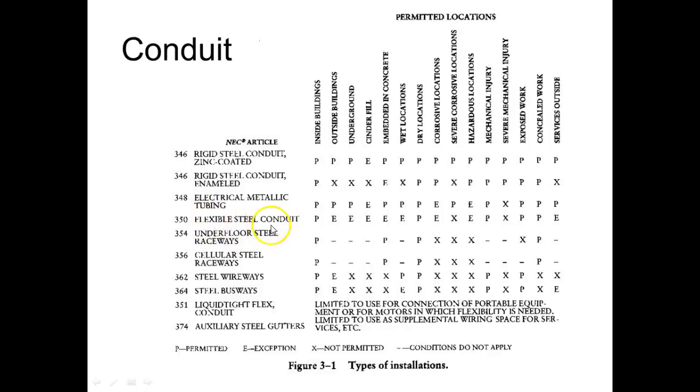Flexible metal conduit. So flexible metal conduit, we use this a lot between things that are going to be in motion. Yeah, so we do have some EMT over here. So this is EMT, 3/4 inch running across that, right? So that's what we call EMT up there. And you can get that in different gauges. The bigger the gauge, though, the harder it is to bend. So we have foot benders. The foot benders are usually for a. Somebody, look at the bend mark.